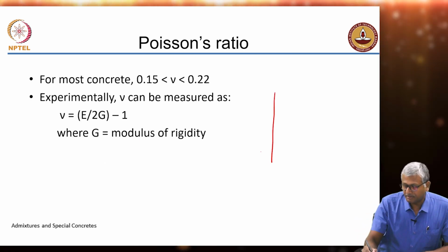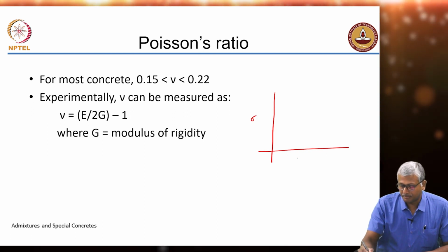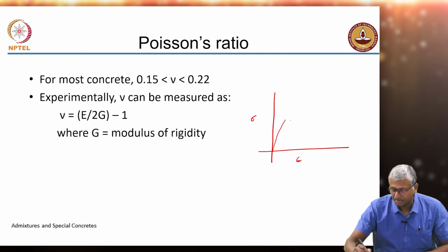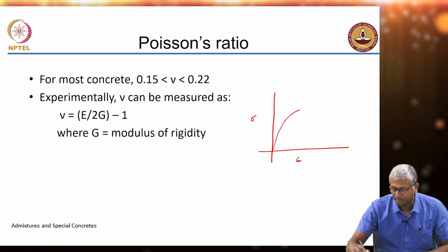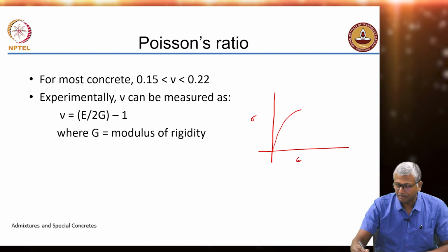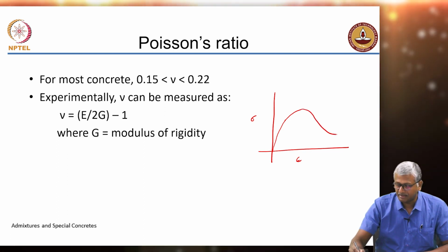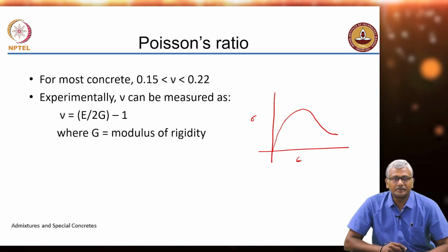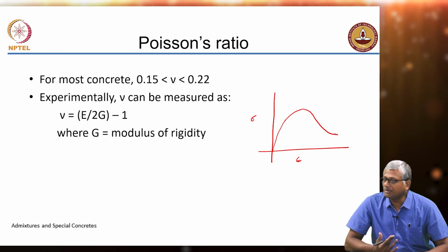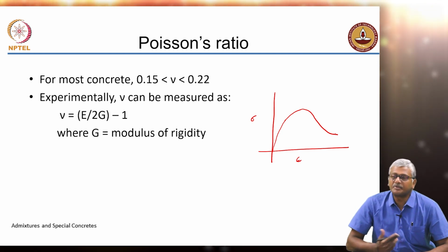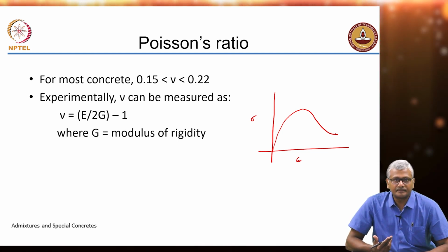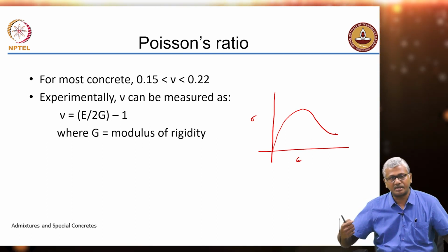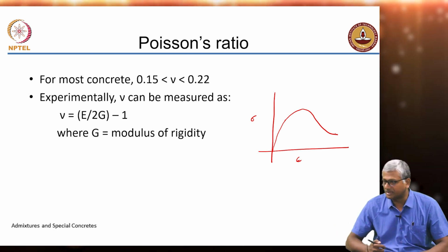Let me just anyway draw the stress strain relationship in concrete. So, typically you have sort of a linear behavior in the beginning, but mostly a non-linear behavior. You reach the peak stress and then there is some bit of ductility beyond the peak stress, okay. We do not call it ductility, we call it a quasi-ductile or quasi-brittle relationship in concrete. It is not like steel where you have a large extent of deformation that can actually happen. In concrete, there is some deformation that can actually happen.